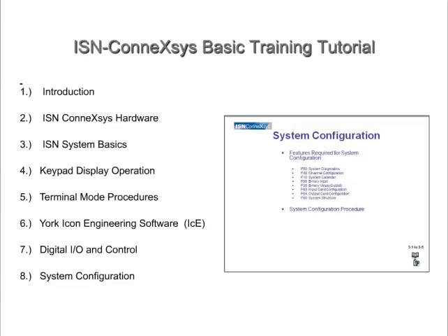After that, Feature 10, System Calendar, is covered, where we set up the real-time date clock parameters. Next, Feature 6, Binary Value, is where we set up our digital output statuses. Feature 63 is Input Card Configuration, where we map in the input devices wired to the system. Feature 64, Output Card Configuration, is where we map in the addresses of the physical output devices that are connected to the system. Feature 60, System Structure, is where you set the operational mode of the controller: run, halt, or monitor. And then we move on to reinforcing lab exercises.